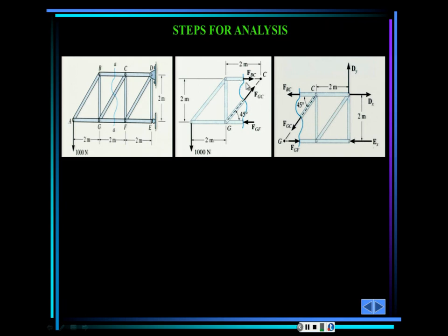The important part is, if you are assuming this force is leaving the joint, coming out of the joint, like we are assuming, which is tension, remember, in the other connected joint, which is the joint C, corresponding to the right part of the structure, it has to be also leaving the joint. You see that? Leaving the joint here, here, here, and here. This part was assumed entering the joint. Well, then it's going to be entering the joint here, and this bar, because we don't know it yet until we calculate it, we are saying is subject to compression.